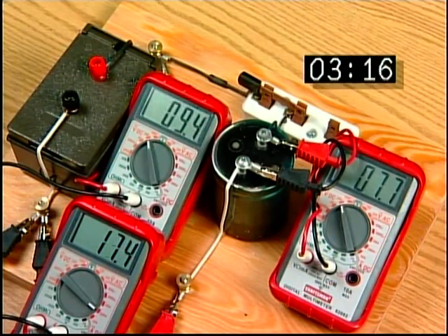That is one time constant. And it takes 5 time constants, in this example approximately 10 seconds, for the capacitor to be fully charged to 9.4 volts. By choosing different values of R and C, the time constant tau can be varied. This principle is used in many electronic circuits for timing purposes.